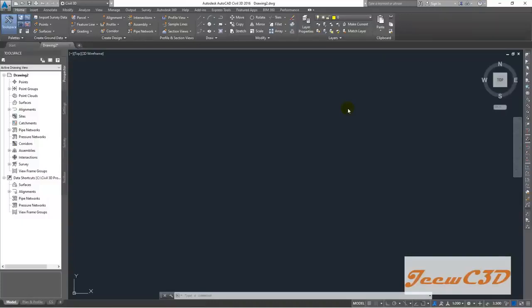The surveyor will get the features in that area as well as the elevations by means of points. So the surveyor goes there and takes elevations as points, and also takes the objects or features in that area. The surveyor will give us the point file where we have the elevations.